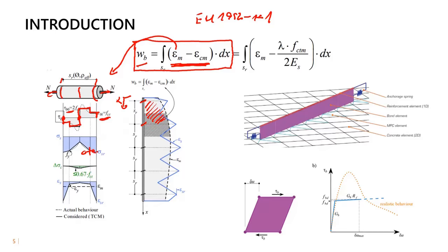Based on that, you can see this is the trend of the stress on the rebars. It is dropping down towards the center point in between the cracks and gives you a lower value on the reinforcement rebars. So the approach implemented in the CSFM is to make it averaged. Using epsilon m, we make the averaging in between the cracks, and this is the first input to this equation.